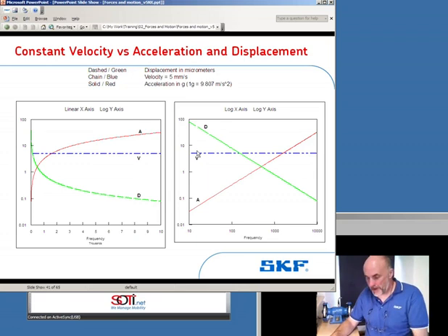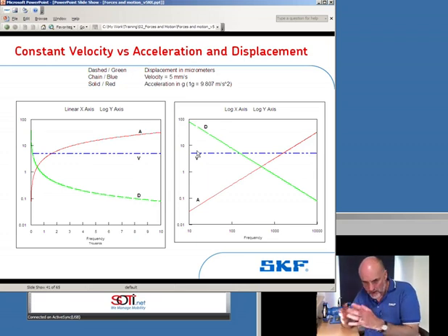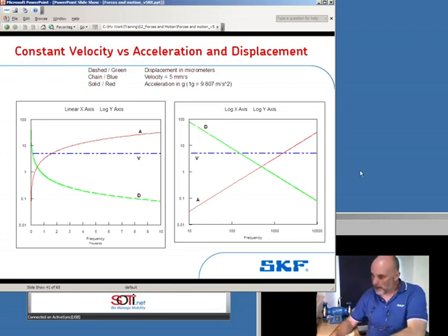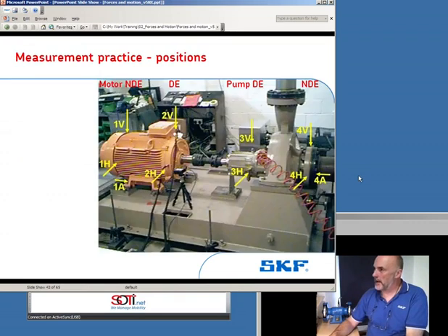If it's a forced draft fan in a power station, 5 thou movement isn't very bad. You expect a huge, great fan to be moving that much. But if it's a high-speed turbocharger, I wouldn't be standing near to that turbocharger because you'd be having lots and lots of G. I think we've got 10 minutes to run and then we're done.